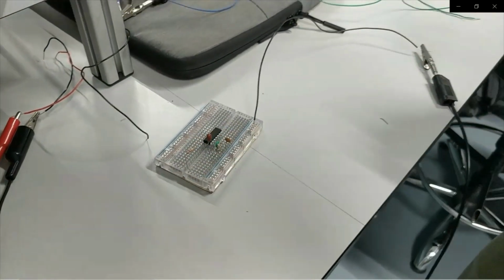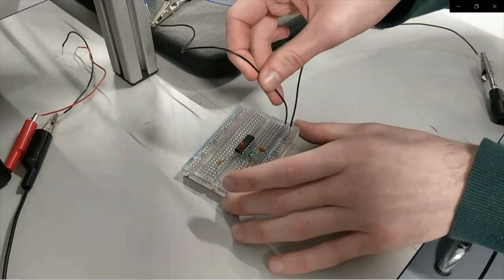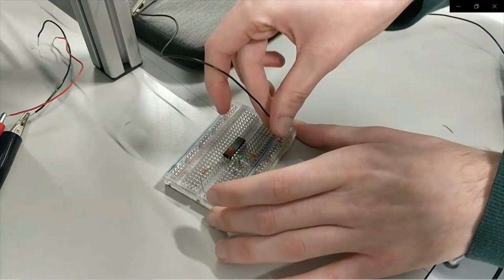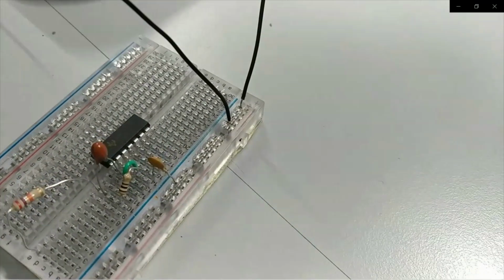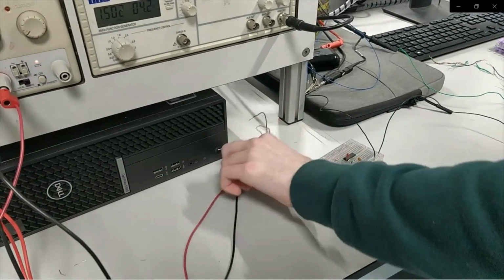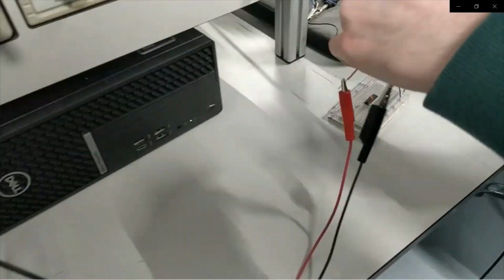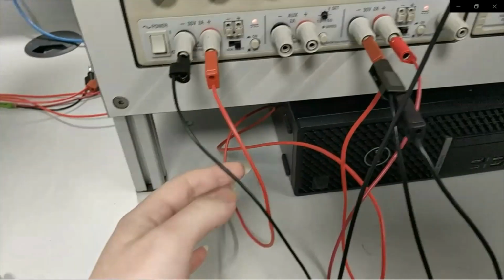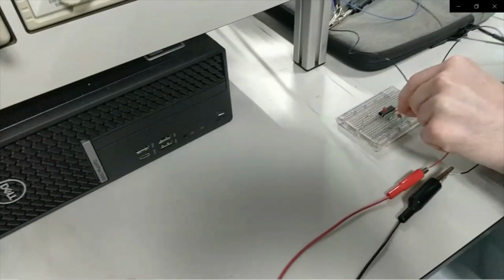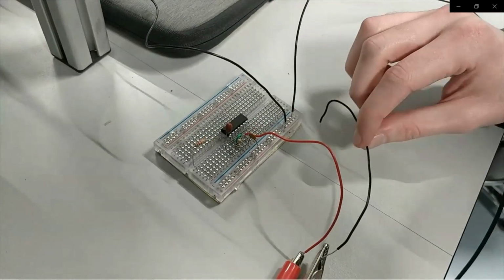From the right we have a positive 10 volts and a negative 10 volts from the left, and we use that ground to ground the circuit, and we attach the ground of the function generator and the oscilloscope to it as well. So there are the outputs of the power supply. The black wire is the negative 10 volts and the red wire is the positive 10 volts, going into the op amp there.